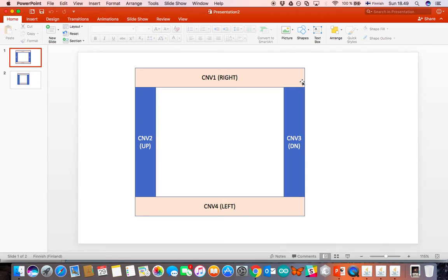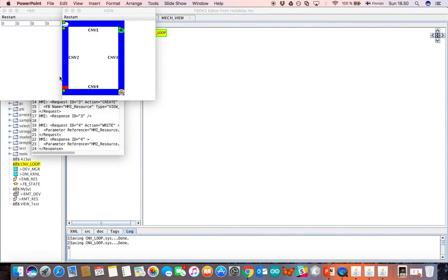So in a way, this is an indirect signal to us that we have correctly specified the orientation of our conveyors. The disk would be going from the left to the right, the ring from the top to the bottom, the peg ring from the right to the left, and finally the palette would be coming from the bottom up. So this can already be seen here; we get the right orientation for that functionality. Good. But let's now interconnect our fields so that as we provide values from 0 to 100, we will see the corresponding objects moving on the conveyors here.